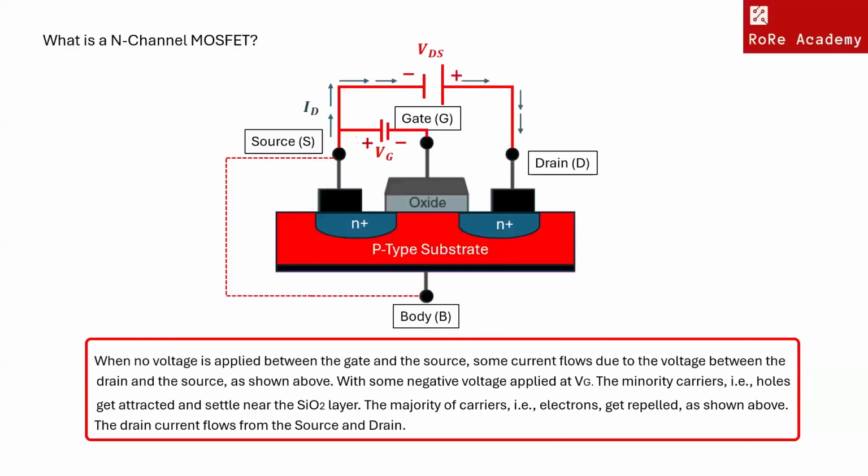When this negative potential is further increased, the electrons get depleted and the current ID decreases. Hence, the more negative the applied VG, the lesser the value of the drain current ID will be. The channel nearer to the drain gets more depleted than at the source, like in a FET, and the current flow decreases due to this effect. Hence, it is called a depletion mode MOSFET.